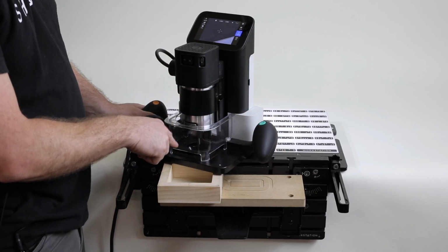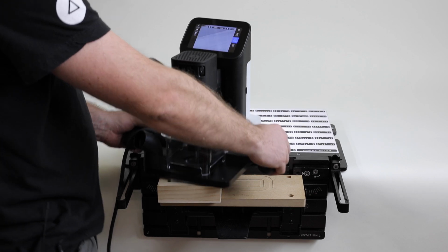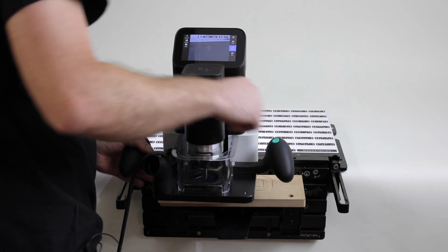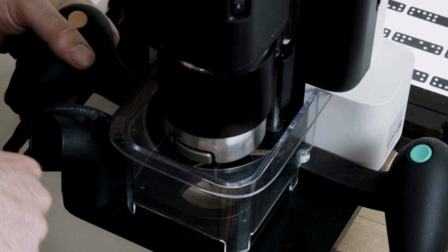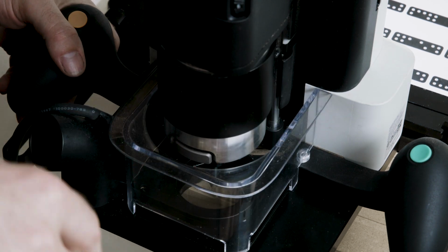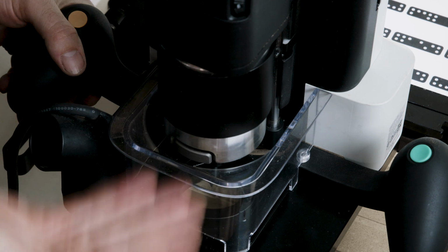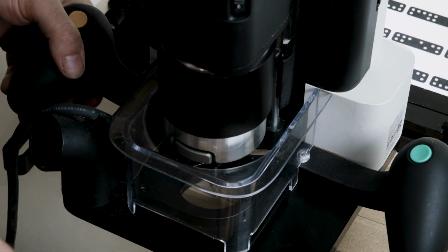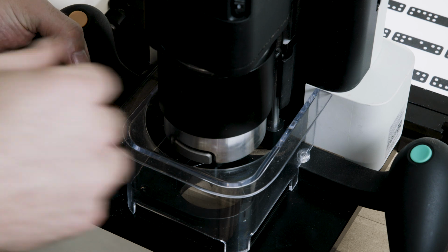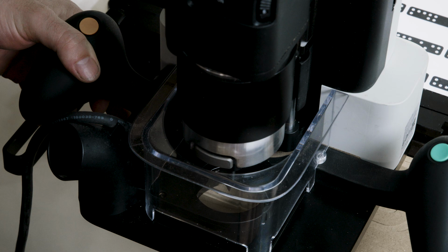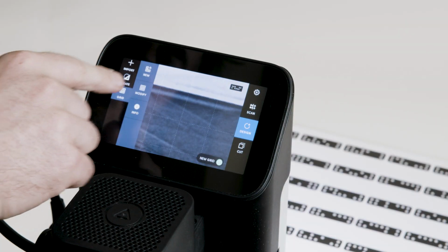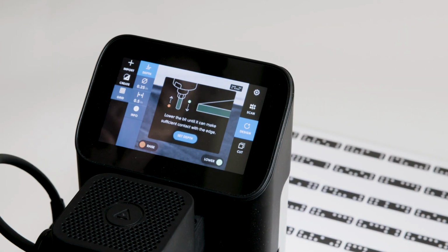Right, so I've got the cutter with the point facing down here. I'm going to come over. Now the cool thing here is we actually have a cylindrical shank if we just go a little deeper than the cutter point itself. So I'll be using that for the first 2 physical probes, and then for the visual probe I'm going to raise up midway through and show you how to visually probe as well. We'll bring the cutter out beyond the edge. We don't want to mar our stock, and then go same as we have previously, new grid.